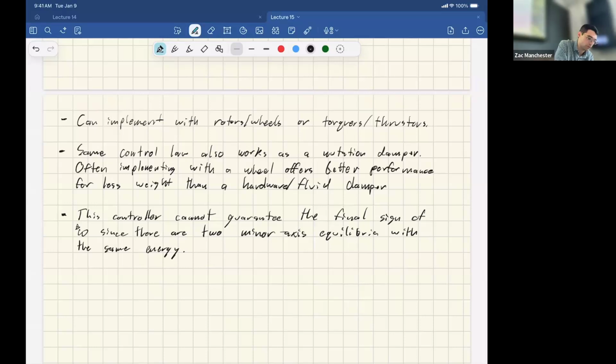Okay, so from here, you can set those up however you want, and then you do the same kind of thing. We can derive a wheel Jacobian. So you have something that looks like this. We have rho, the body frame, and it's just the wheel axis unit vectors for each wheel. So we'll call this A1, A2, up to AN for N wheels.